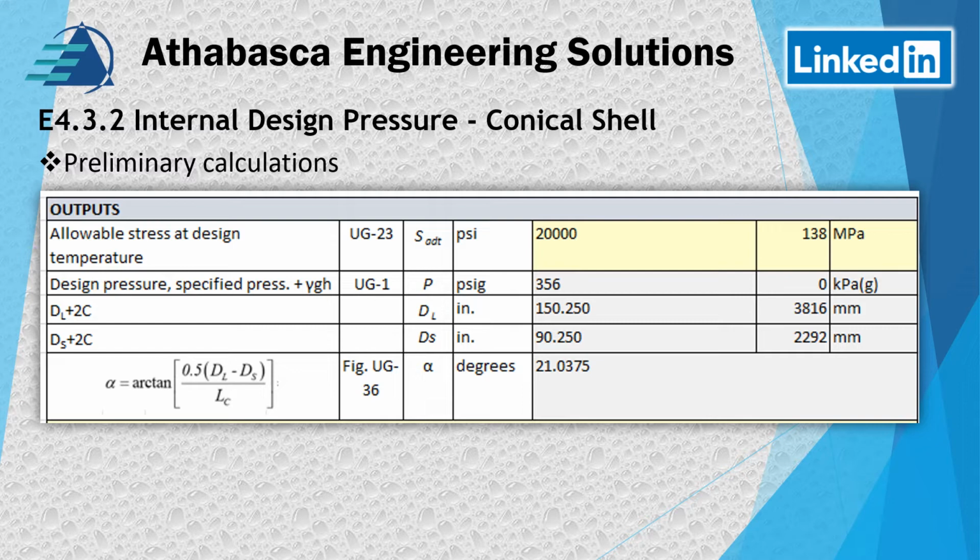the tan angle. In this case, we've got a concentric one, but if you had an eccentric one, you do that equation twice and you find your maximum. So in this case, we have 21 and a very precise angle, and this is just to show you that this matches the example exactly. So that's how we basically do it.